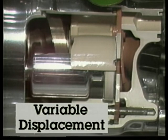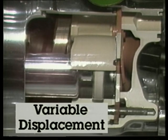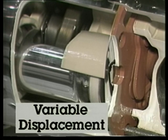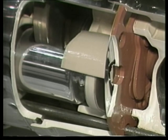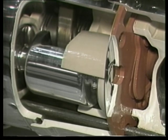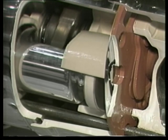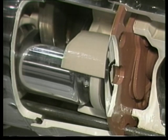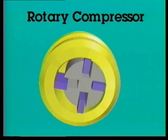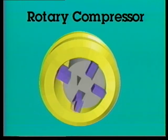Some wobble plate type compressors are variable displacement. The wobble plate can be moved to change the effective stroke of the pistons. This provides for more efficient operation, reducing fuel consumption and power loss. Another compressor design is the rotary compressor. It uses sliding vanes in an offset cylinder to produce a pumping action.